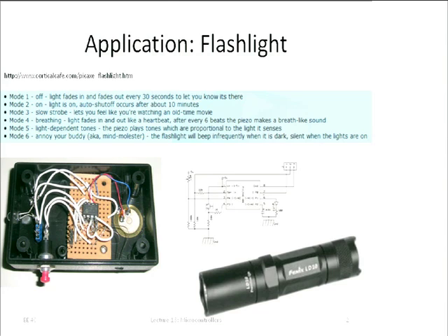Well, I searched around the web, and some people, they didn't want to pay the $50, I suppose, and so they built it themselves. And what is in here looks like a 555 timer, it almost is a 555 timer, but it's actually a microcontroller. What does it do? Well, under program control, it turns the light on and off, of course, at a very high rate, right? And also inside it keeps track of the time, and after 10 minutes it turns off the light, and you have to switch it on manually again.